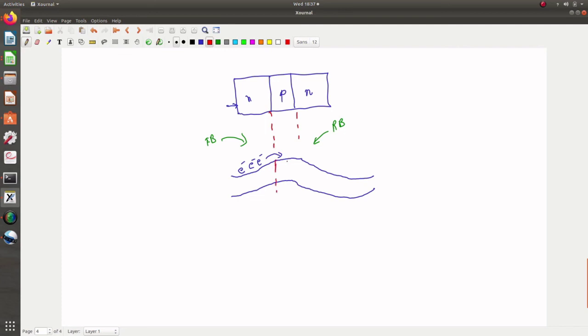In the energy band diagram, this is the emitter, base and collector sides. The electrons reaching the base will recombine with holes here, and whatever electrons remain on reaching the reverse biased collector base junction get swept to the collector.